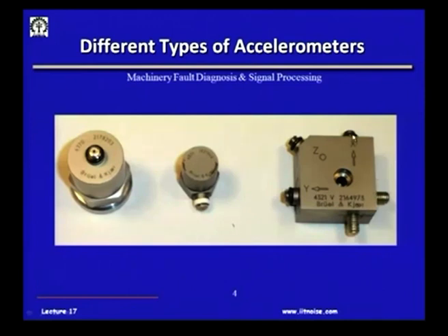So, X means the cable connected out of this location is measuring the motion in the x direction. Z means it is out of the plane of this presentation here, and Y is in this direction. So, you can think of it that 3 piezoelectric crystals having mutually perpendicular orientations have been put together, so that at one point I can measure the vibration in 3 directions.